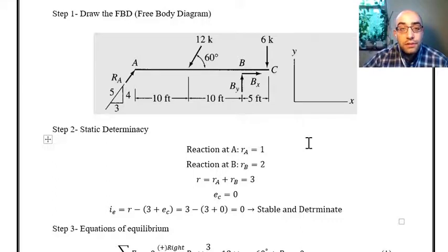The other parameter that we have is EC, which is equations of condition. As you may remember, during the presentation files, we said that if we have a roller in the middle of a structure, EC is equal to 2, because for that roller we can say summation of forces in X is equal to 0 and summation of moments about the roller is equal to 0. So whenever we have a roller in the middle of a structure, we can say EC is equal to 2